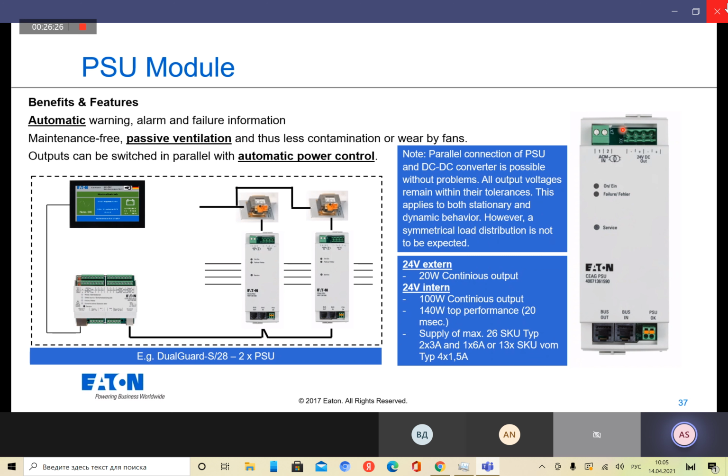You might recognize that we don't have a dip switch anymore here. You cannot turn this module on and off with this dip switch we all know from the DCM. If you would like to turn on the module, or you would like to turn it off, just press the service button for 4 or 5 seconds and the system will turn off or on.